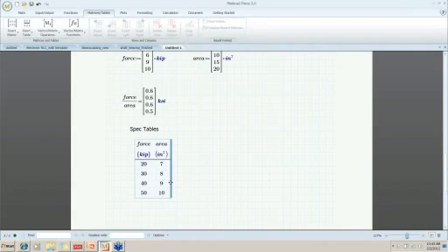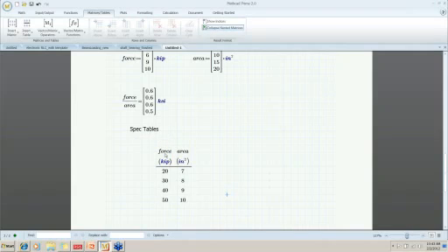Force is now the name of a variable. These column headers are intelligent. Force is the name of a variable that stores this column of data with units of kips. Area is the name of a variable that stores the second column of data with units of square inches. So these column headers are intelligent column headers. They mean something. They store data.